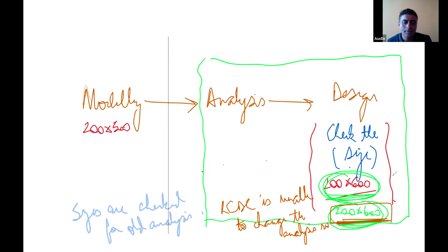So you have to be very careful that if you are changing the size in RCDC, because RCDC does give you this option, you should update the analysis file and recheck the size again.